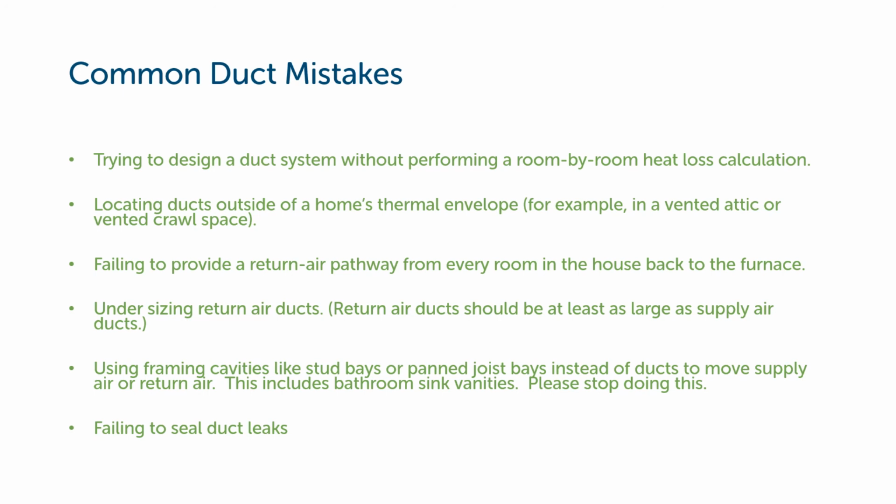Using framing cavities, don't do this. We talked about this, like panned joist bays or stud cavities. And this includes bathroom sink vanities. I see a lot of people, they just come up through the floor and they don't even put a register on it. There's just an open boot in the floor under the bathroom vanity.